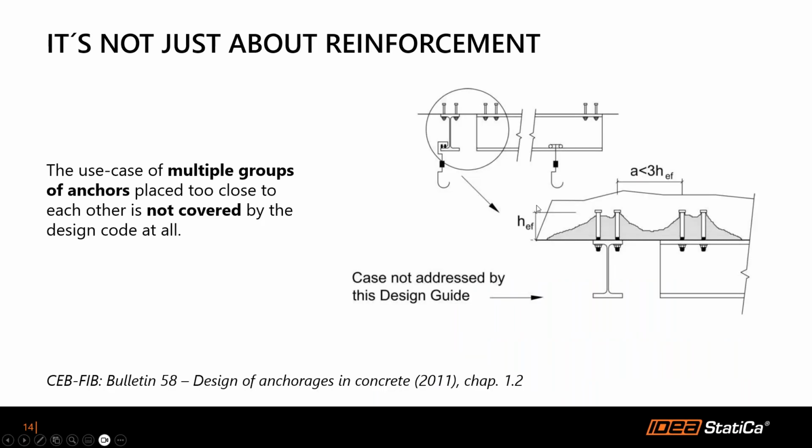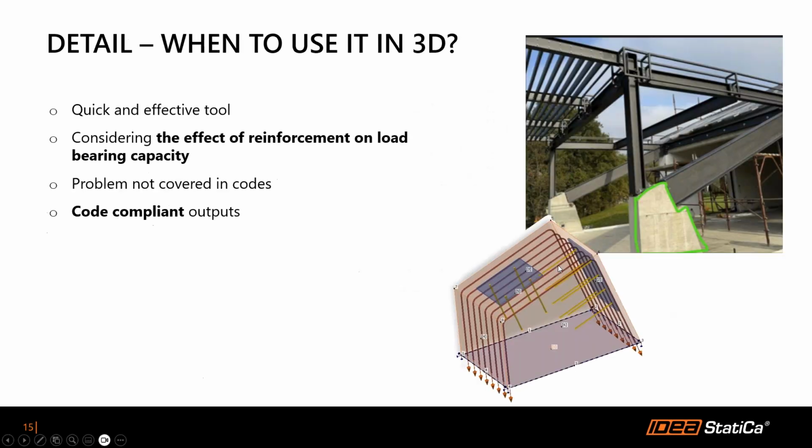And another challenge, I would call it, arises when anchors are placed in close proximity to one another, creating a shared concrete cone. Now, this scenario is not thoroughly covered by the design codes, so we must address it separately. And this brings us to why Idea Statica is such a valuable tool.